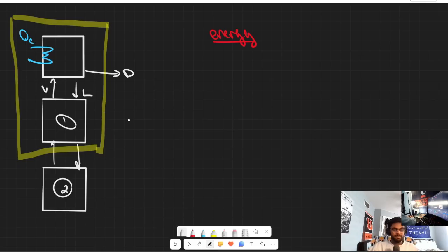So of course we have a vapor and a liquid flow stream here, and we have a distillate flow stream here. We also have this Q cooling that is being fed into our system, you could say. It's being used to take that vapor back into the liquid form to then be used throughout the distillation column. Some of that will be distillate, some of that will be liquid, determined by the reflux ratio.